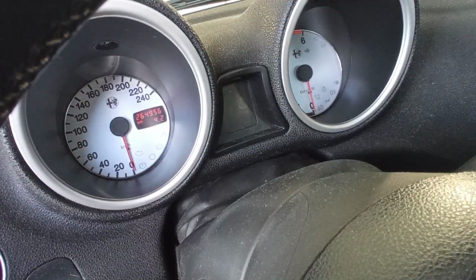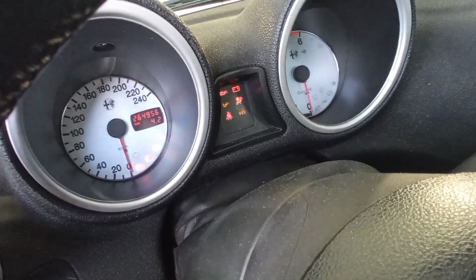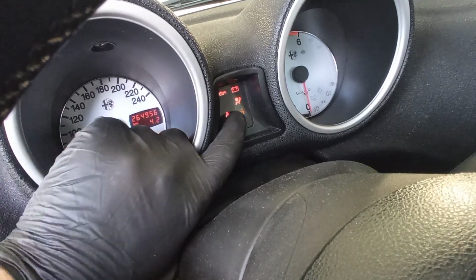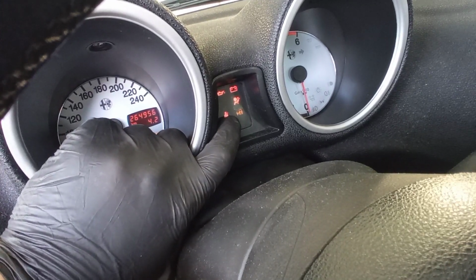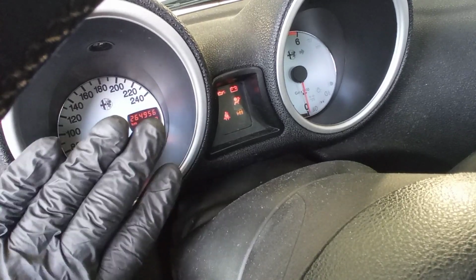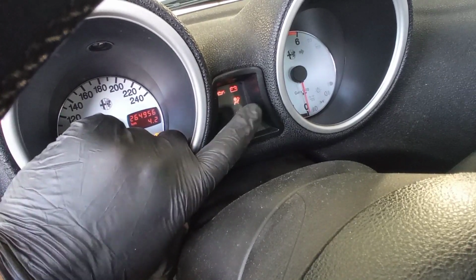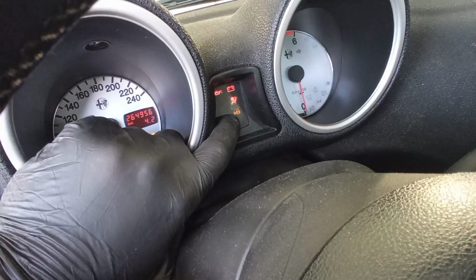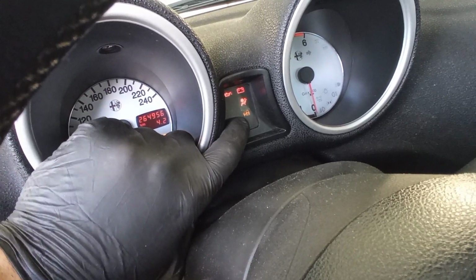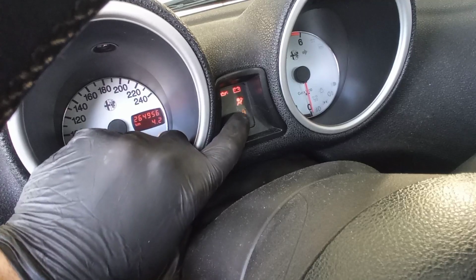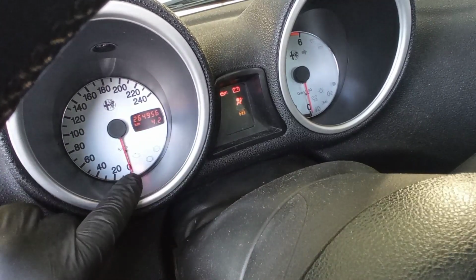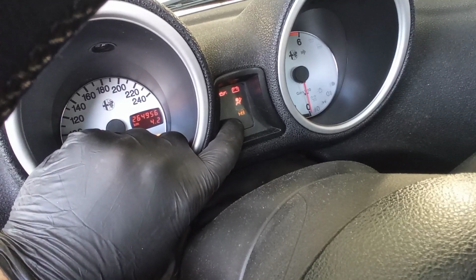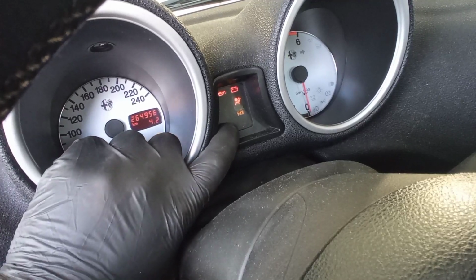So another problem related to this earlier one: you switch on your ignition, your engine light does not turn on, but your immobilizer is always on. Now, this is very easy to fall into a trap, because at this stage you want to do a diagnosis on your immobilizer, right? And it will tell you a lot of fault codes about the ignition, the key is not programmed, and so many things, and the problem is really not in there, okay? And then you try to erase the immobilizer or delete it in some way, and the problem persists.